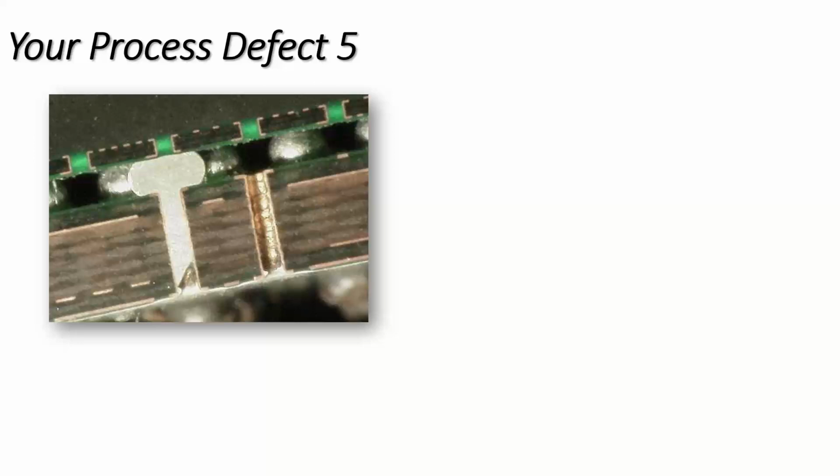If you looked at this first of all and knew this was a microsection of a BGA, you would have thought that the solder between the BGA package and the board was actually a ball, but it isn't. What's actually happened here is the solder has gone up the via, wetted it, and formed a ball, possibly not a short, on the underside of the BGA, so sandwiched between the BGA and the PCB.